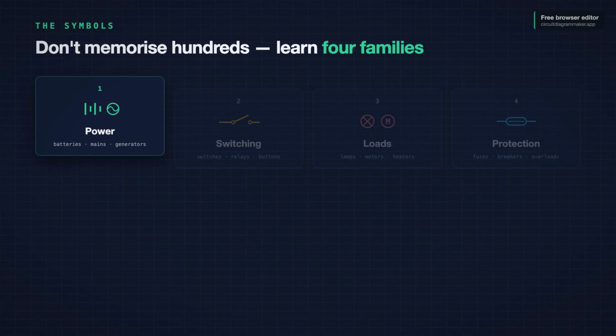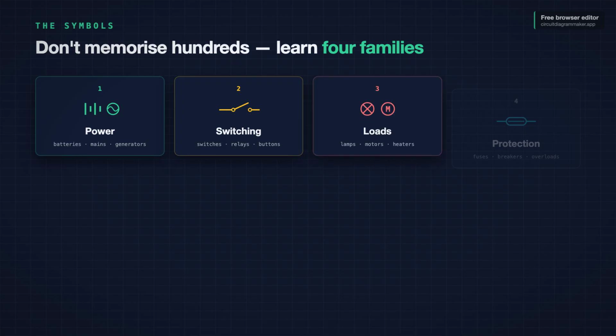Family 2 is switching. Switches, relays, contactors, push buttons, anything that opens or closes a path. They are drawn as a break in the line, with something that bridges the gap. Family 3 is loads. The whole reason the circuit exists: lamps, motors, heaters, coils. Anything that turns electricity into light, motion, or heat.